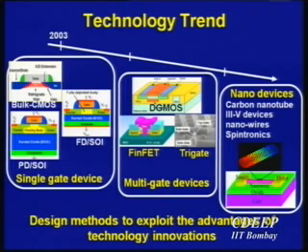So on the other side, you have these nano devices. I shouldn't really say nano devices because all these are nano devices. These are silicon nano as opposed to non-silicon nano. So if I look at some of these non-silicon nano devices: carbon nanotubes, III-V devices, nanowires, or spintronics. Those are all different possibilities that people have been looking at, and there are some interesting aspects associated with each of these devices. Higher mobility, for example. In a carbon nanotube device, there's a potential that you can actually get all-around devices and so on. But unfortunately, at the moment, trying to replace silicon with any one of these devices is not there yet, right? And there's still a lot of work required to get there.